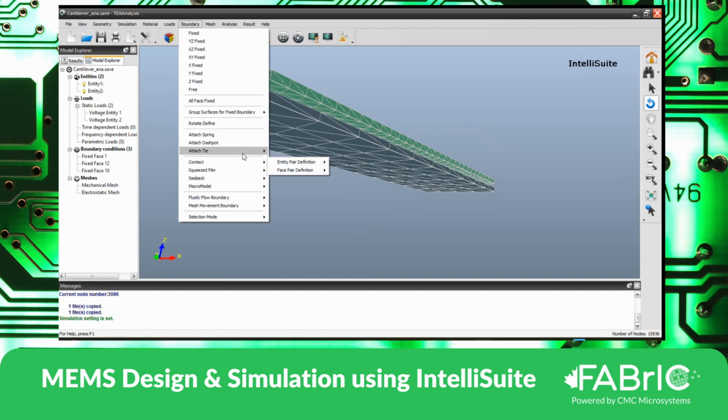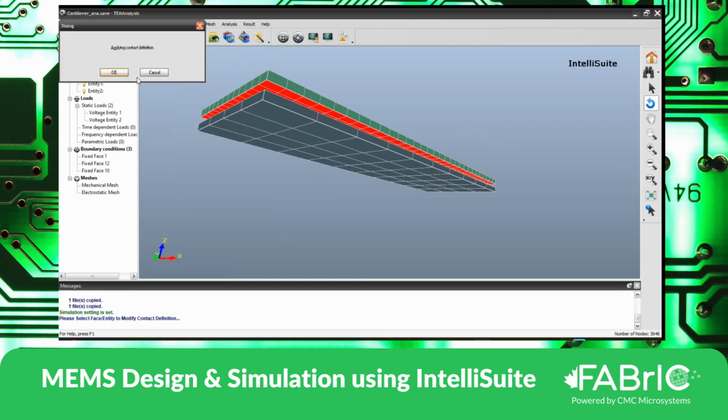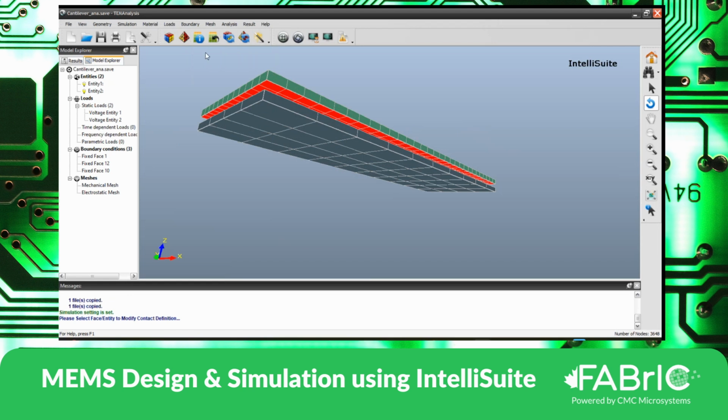I go to contact and then face pair, and in face pair, face A. So this bottom is my face A.